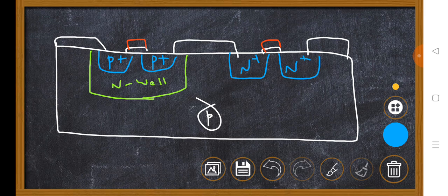But anybody, will you please tell me, when you are exposing p-type impurity gas here, here also the p-type impurity gas will be exposed. Then what will happen? Here the p-type will form, here also the p-type will form. Therefore don't forget, you have to mask when you are diffusing p-type. At this position you have to mask. When you are diffusing n-type, at this position you have to mask. I hope you are clear. This is an important point, don't forget this.